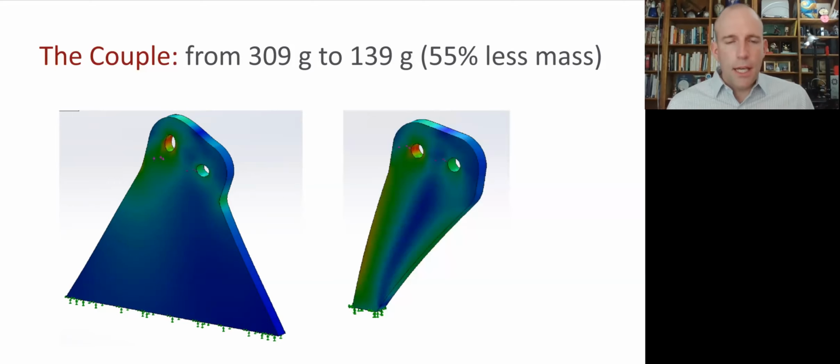and we can optimize for that. If instead there are a bunch of different types of loading that we expect it might experience, we should model those and then understand what shapes would be good to prevent failure in those cases, and then make one part that incorporates all of those features. And that generally results in a less specialized optimal shape, but still an optimal shape.